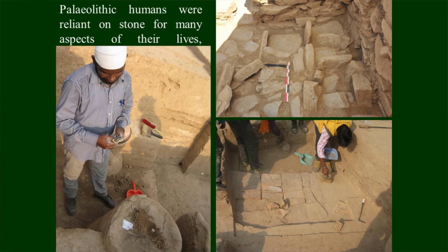Now, when we are talking about floods, can we date the floods or see the cyclicity of floods? For that, we have to go into the past. Again, we have to look for sediments within these terraces, and these terraces will give us the age of the event when they were formed. So if we have multiple aggradational events, we can work out a cyclicity, or a time frame when the floods have happened and when they can occur in the future.